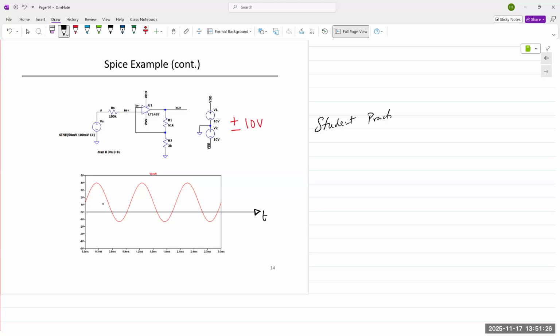So, I strongly urge you to do that. Okay. Take an op amp, connect it in a non-inverting configuration, apply an input voltage. You can play around with the parameters, apply a DC offset, positive offset, as is shown here in the slide. You can apply a negative offset. You can also remove the offset completely and see how the output changes for different DC voltages. Okay. All right, let's take a pause. Let me know if you have questions.